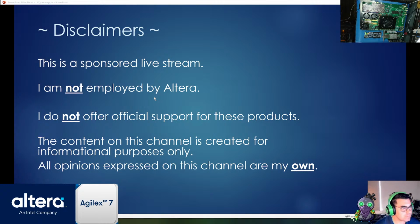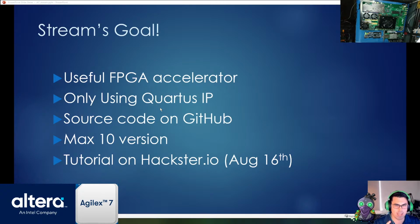Agilex 7 board. And today we're going to be looking at doing a very basic FPGA accelerator. For this example, we're only going to be using Quartus IP, specifically the Platform Designer. I want to demonstrate how you can rapidly prototype an existing accelerator with their block-level Platform Designer tools. We're going to do a basic one today with JTAG driving everything, but you could easily look at Ethernet or some other type of interface to bring data in and out of your system, or HDMI output for video.